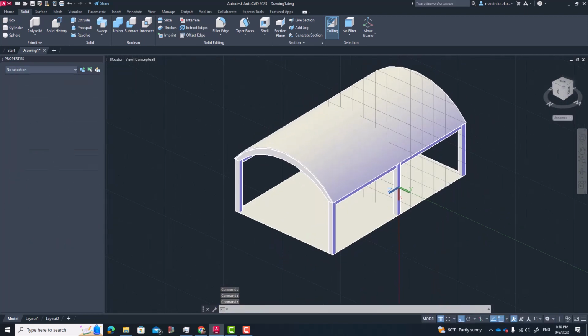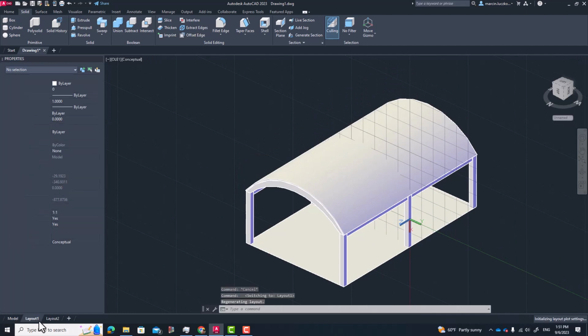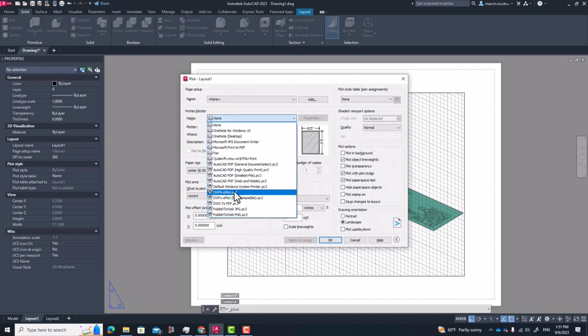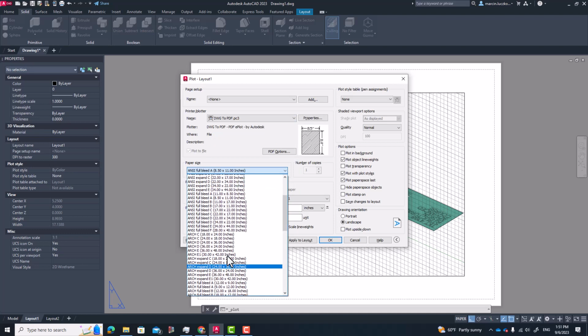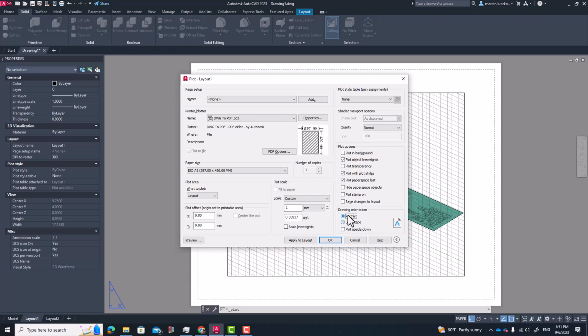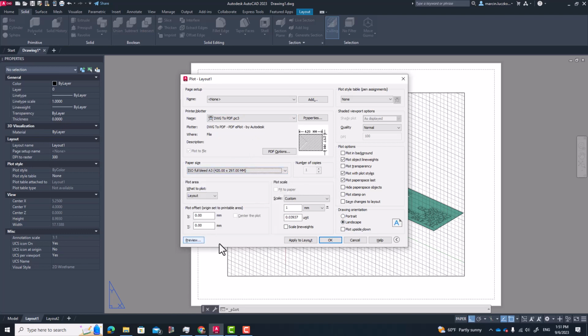Okay, just to finalize and make it clean and clear, the last thing I will make the layout. So generally in the layouts, as you know, you can create many, or you can adjust to the paper. So first I will click Ctrl P. I will specify DWG to PDF. I will set it up to be, for example, A3 paper. Let's see where we have A3 here. I will use the portrait landscape. Maybe I would like to be A3, this one. Okay, perfectly.